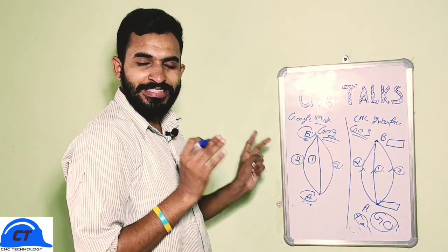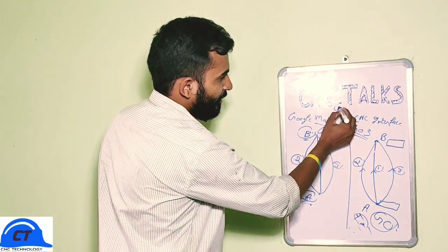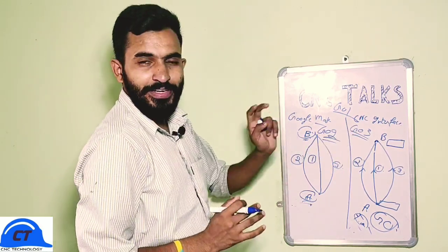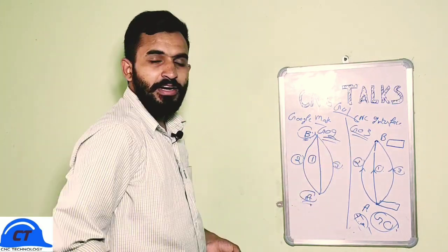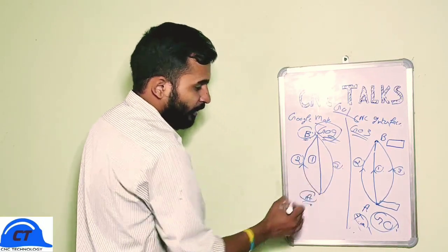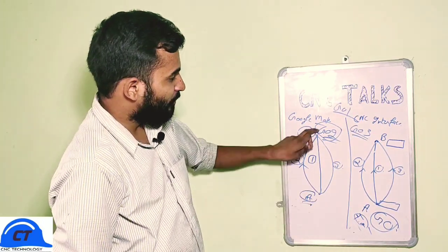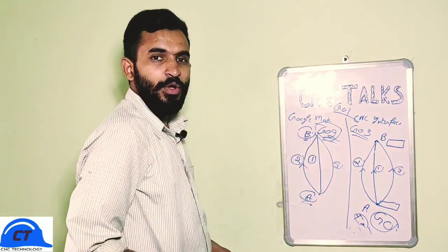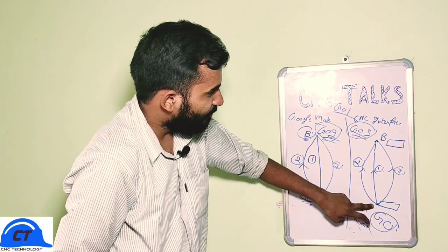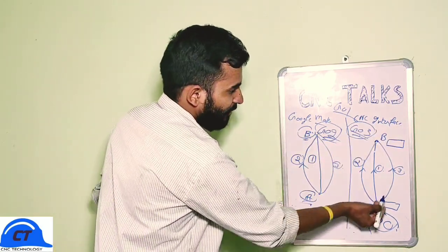These codes are exactly similar to G01. Like G01, we can use feed rates in both the cases. We'll use G02 for part 2 to travel from point A to B in clockwise direction, while we'll use G03 to travel from point A to point B in anti-clockwise direction.